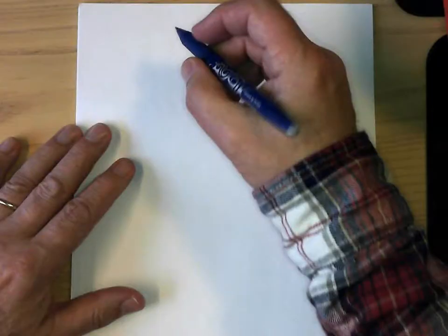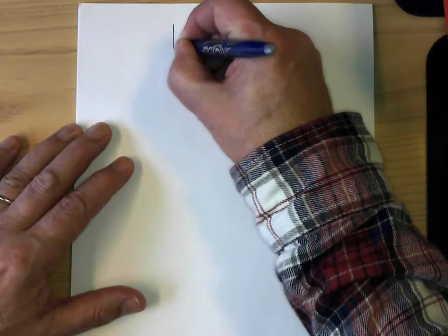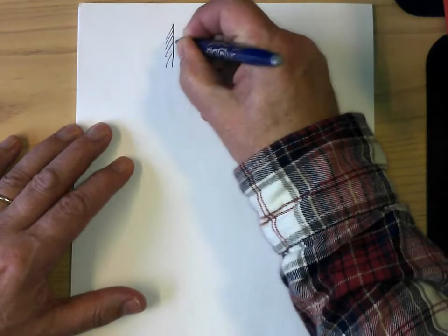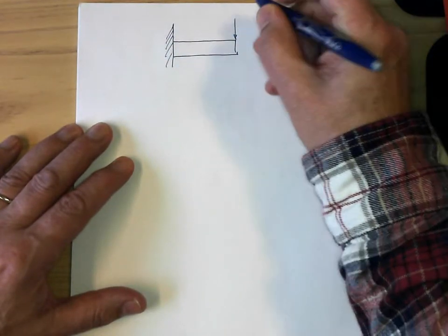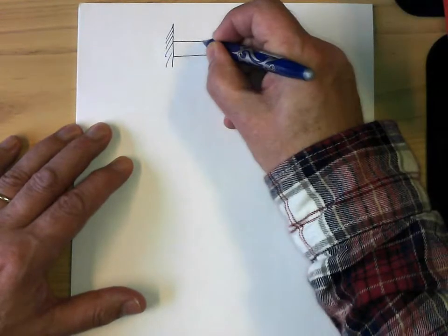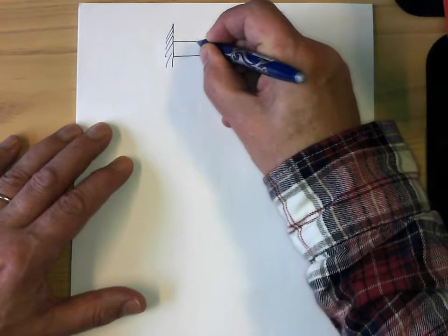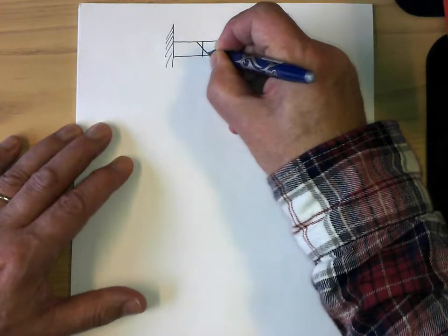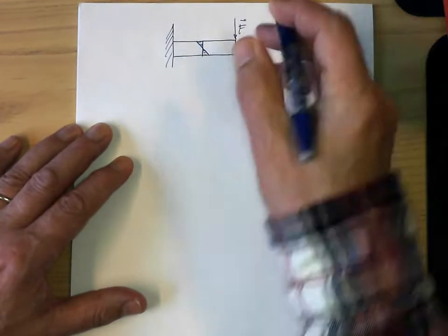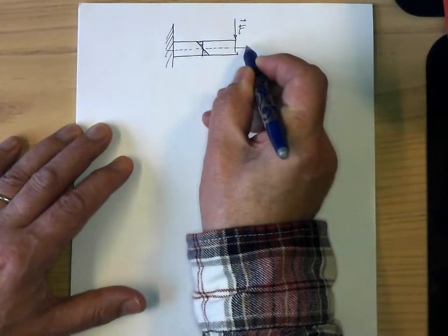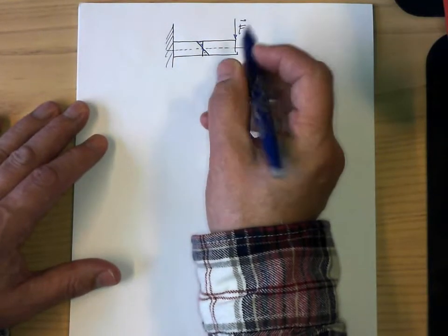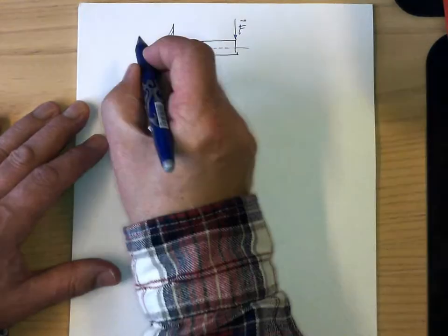Hi, welcome. I want to show you how you can calculate the center of gravity of an area, and we start with a beam which is fixed in a wall, and we have a force acting on this beam, and we are interested in this stress distribution. In one model we can say this, we have this linear distribution of stress, and the neutral axis is defining the position where the stress is zero, and the neutral axis of a beam is in the center of gravity of the cross-section.